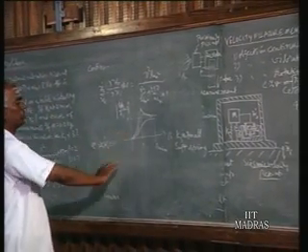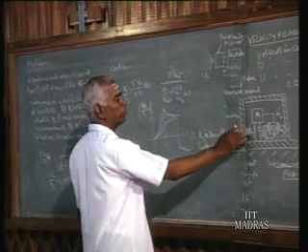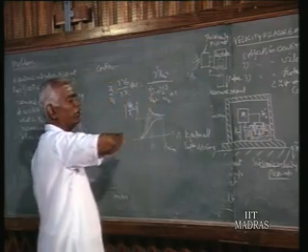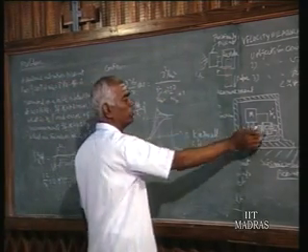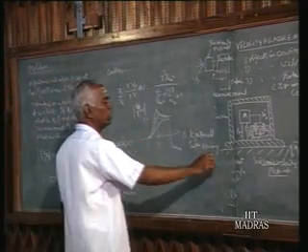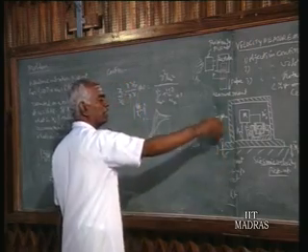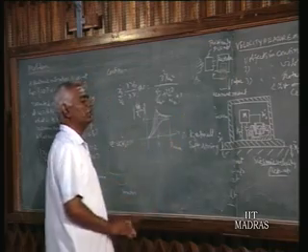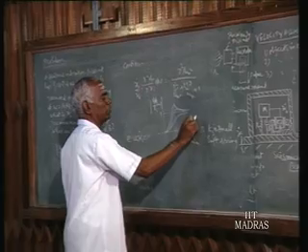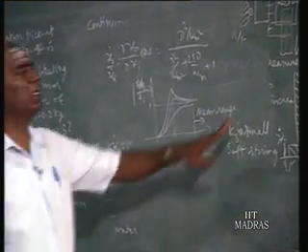So under the same situations, we can also measure the relative velocity of the body. The only difference between displacement and velocity measurement is the instrumentation for measuring the relative motion. Earlier we had something like an LVDT, but here we should have the moving coil or moving magnet, so that relative velocity is measured and interpreted in terms of the input velocity xi dot. We get it in terms of xo dot. That is possible only when beta is more than beta minimum, the measurable range. So these are the various methods used for measuring vibratory motion.